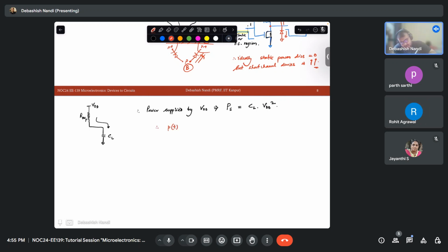Okay, let us see. This PT, we are talking about what power the source has supplied. So we'll take the source voltage and multiply it with the current. By the way, this is your energy, not power. So PT will be VDD times IT. IT is the current that is flowing. So what is your IT? IT is CL dVout by dt. Let's say this is Vo of t, dVo of t by dt.